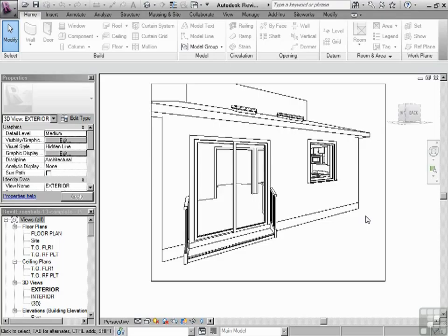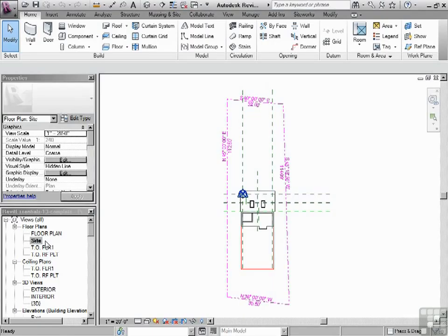It's pretty sparse right now. We've really been concentrating mainly inside the building. So let's look at how the outside can be spruced up a little bit with some topo surface and with trees. We're going to start with a topo surface command. Number one, we want to go to the site plan. That's the first thing you have to know about sites and about the topo surface command. Then in the ribbon, we're going to go to massing and site.